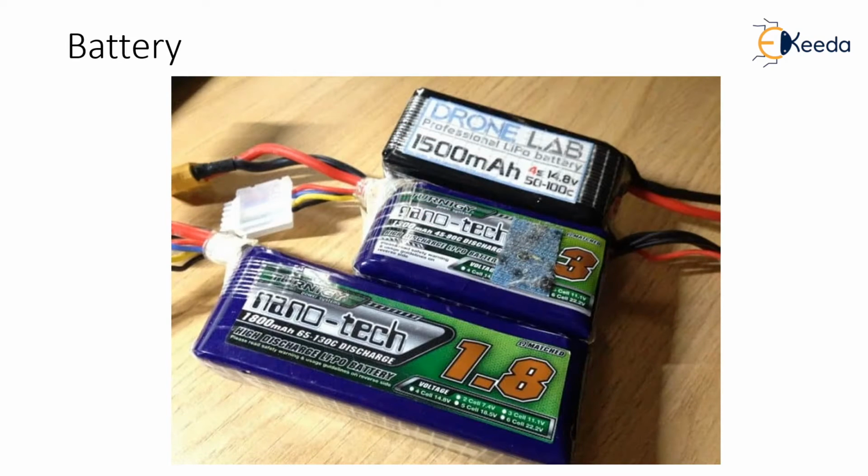When it comes to mini UAVs, micro UAVs and smaller format UAVs, the most common method of power is lithium ion batteries, in configurations that power the electric motors. Common requirements for UAV batteries include high energy to weight ratio, high discharge rates, 5 minute to 2 hour missions, resilience to shock and vibration, and fuel gauging to indicate remaining mission time.